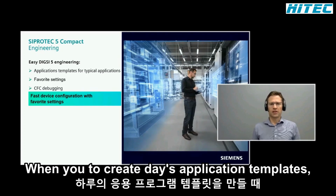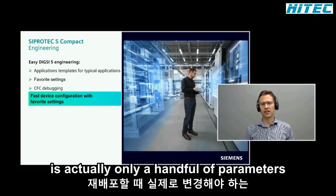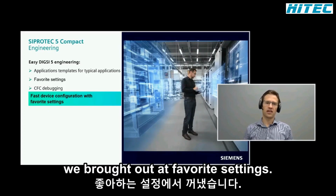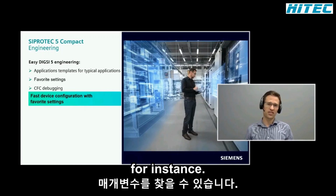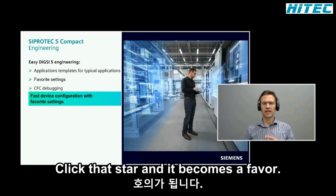When you do create these application templates, you'll often find that when you redeploy them, there's actually only a handful of parameters that need to be changed. For this, we've brought out our favorite settings. So when you're developing the template, as you find the parameters that you need to change on a regular basis, for instance, the overcurrent pickup, time multiplier, and curve type, there's a little star adjacent to those. Click that star and it becomes a favorite.